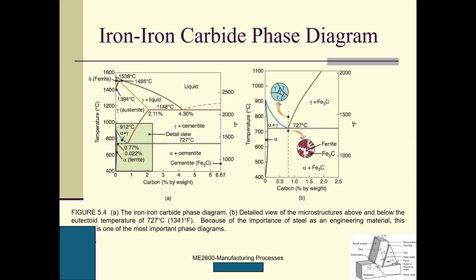So they found that right here, this is the carbon percentage by weight. And here means the pure iron, when the carbon equals 0. Now I'm only talking about ordinary steel. I'm not talking about any other alloys, only steel. Here is pure iron, which has 0% of carbon. And here is 6.67% of carbon.